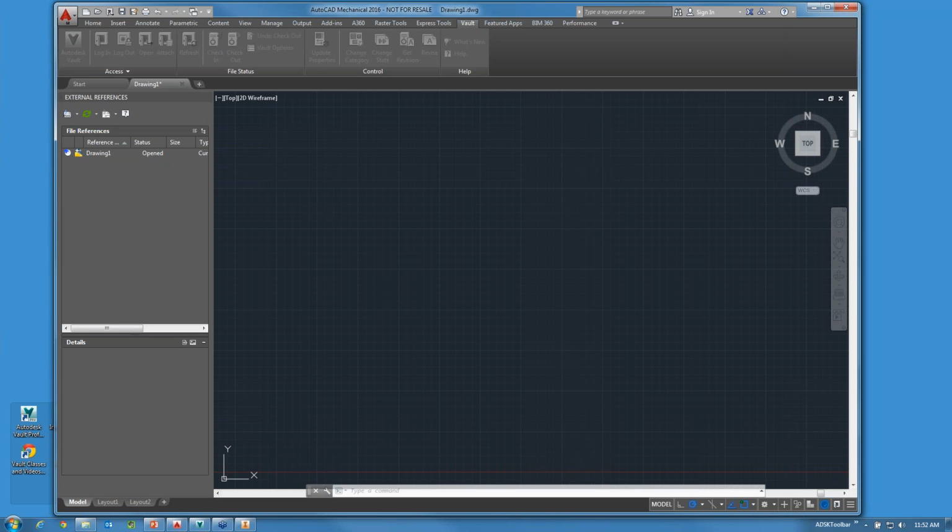What we find a lot of times when we're moving data off network drives are missing, broken references that typically point back to files that may be sitting on somebody's C drive, and that's a reality. So the best thing to do is have a scanning tool to scan your data, and it will produce an error report, and then ultimately you'll go through and work with your teams to find those errors and resolve them. In some cases, it's crap in, crap out. You just have to live with it, and then as you come across the problems and as you modify them, then you fix them. Moving data can be challenging, but it has to be a stepped approach.